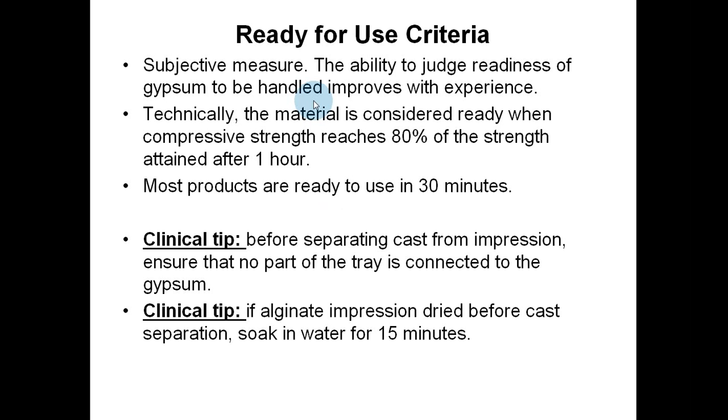The ready for use criteria. It's a subjective measure; the ability to judge readiness of gypsum to be handled improves with experience. Technically, the material is considered ready when the compressive strength reaches 80% of the strength attained after 1 hour. Most products are ready to use in 30 minutes.